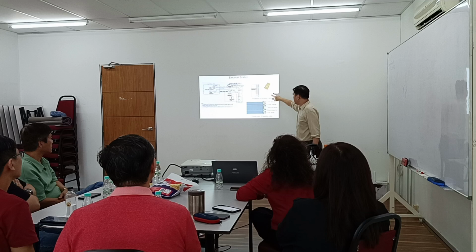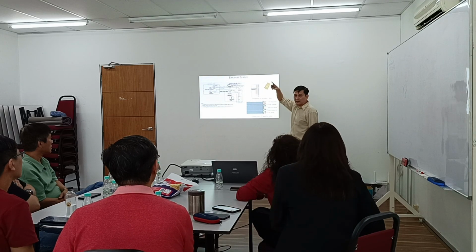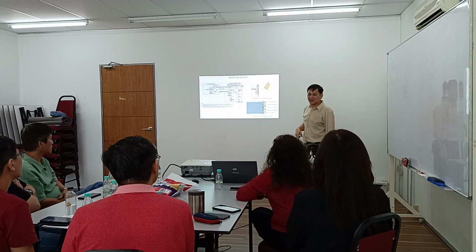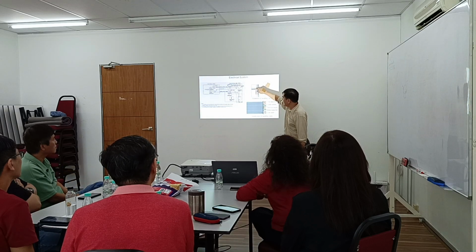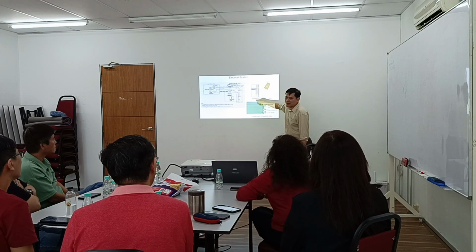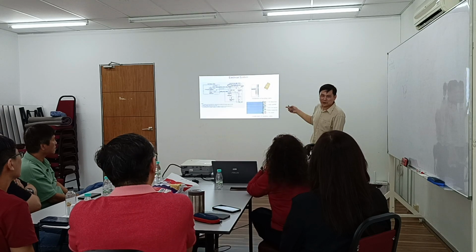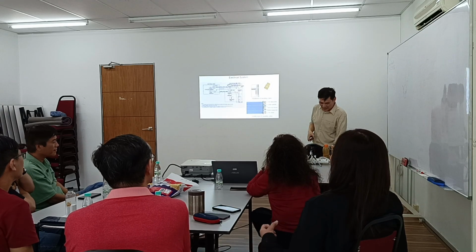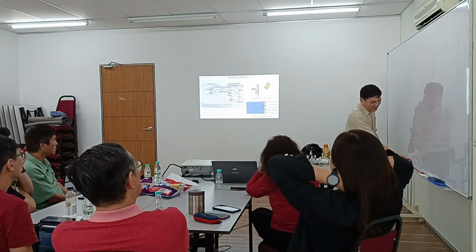So this is the traveling cable. The traveling cable actually does not hang from the top. It will hang from half of the lift shaft, then the lift car only carries the weight of half of it. That is also engineering. Then how does it move up?